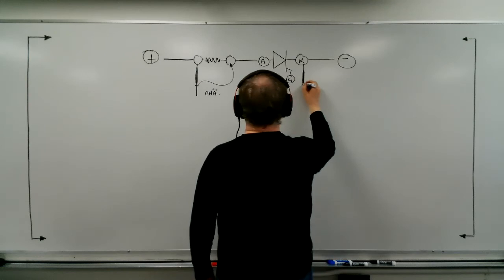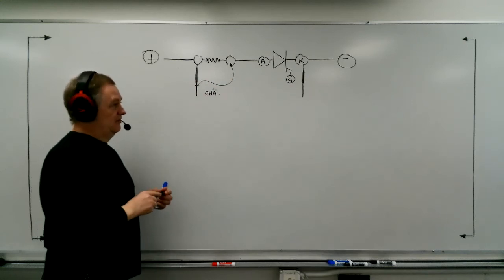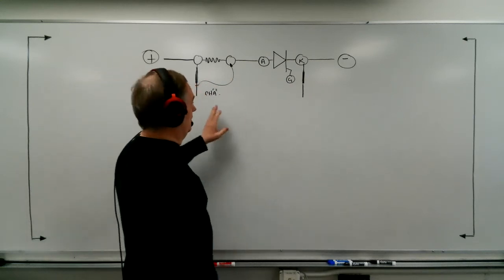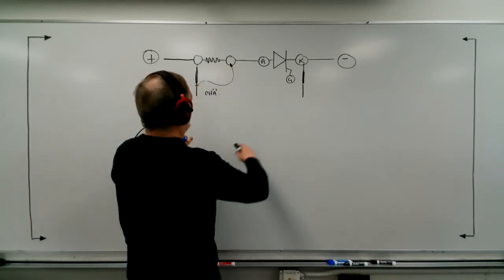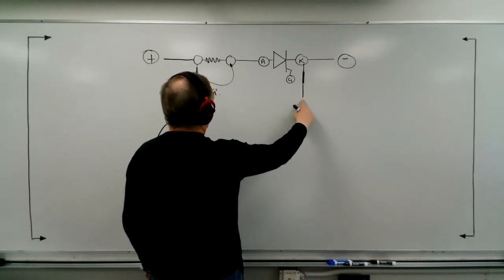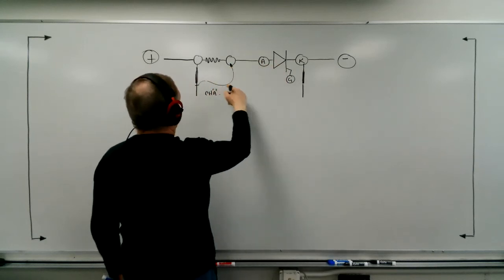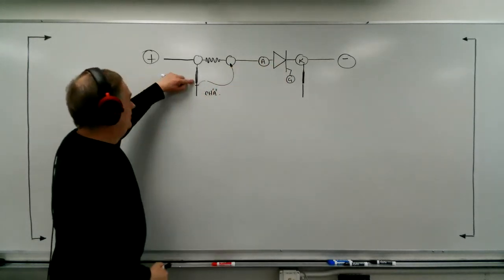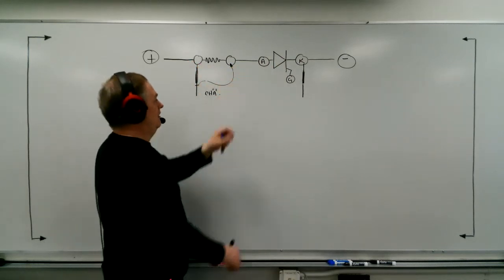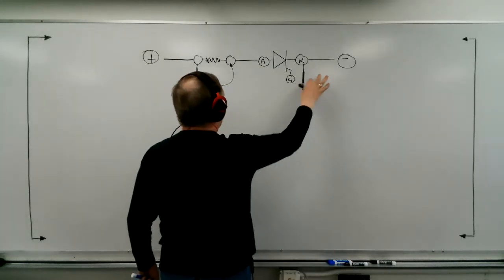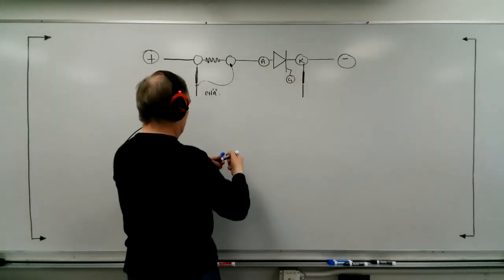And the interesting thing is that, in the lab, this is something that you need to pay careful attention to, and you'll notice it as I'm doing the lab experiments. When I use 2 channels, you only use 1 ground. So in other words, this lead will show me something on the scope with reference through this SCR to this lead right here, which is on this point. And this channel will show me what's on this load up to this lead. So the common lead is in the middle. If you use a second ground lead on this, then you create a short circuit and it'll actually blow the fuse in the power supply. So one channel here, this is going to be channel B, okay?